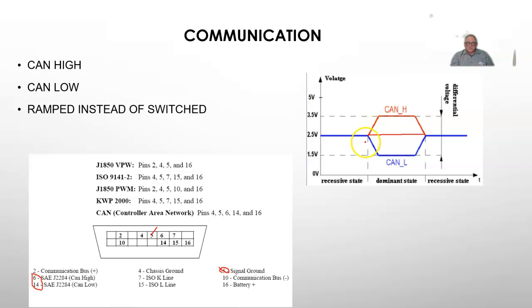When Washington State was doing their emission testing, a lot of vehicles failed the emission test because of no communication. Most common problem, pin 16, which has nothing whatsoever to do with communication. But for some reason, that CAN network that the PCM talks on, if there's no power on pin 16, it won't talk. First thing to check, if you have a no communication, pin 16. Pull the penny out of the cigarette lighter, replace the fuse that got blown. Most of the time that fixed the communication problem.